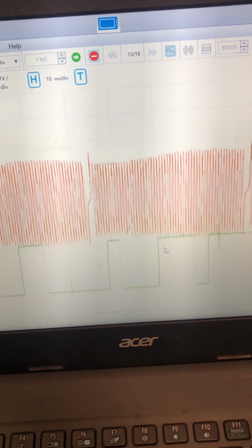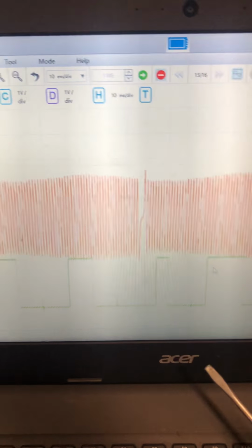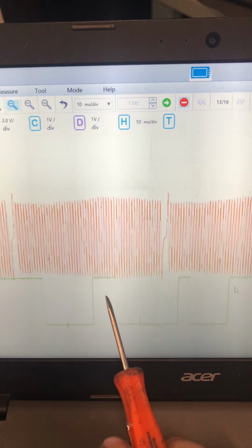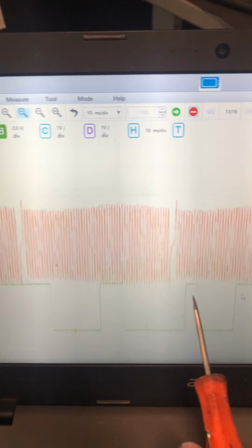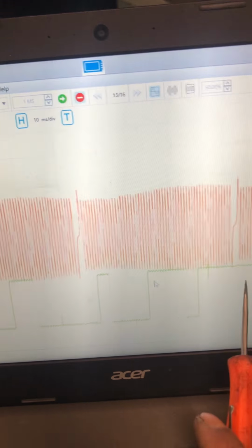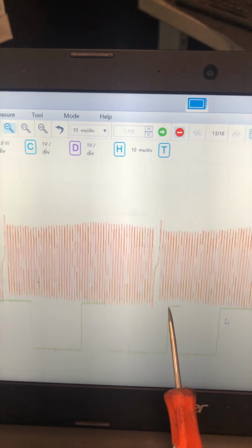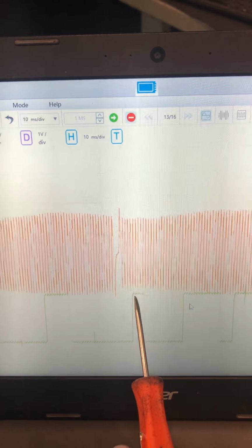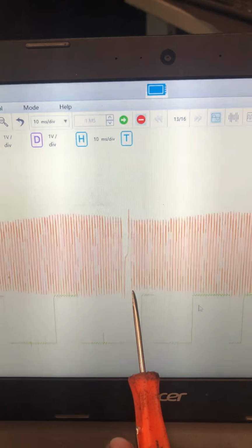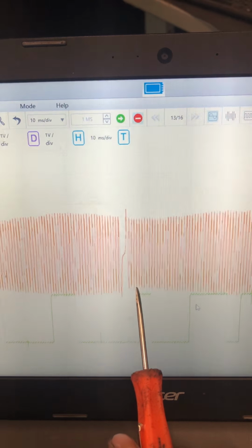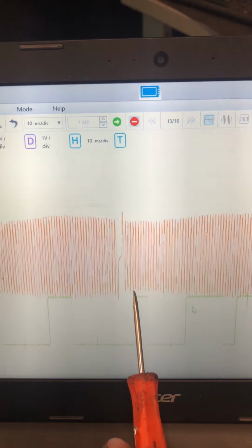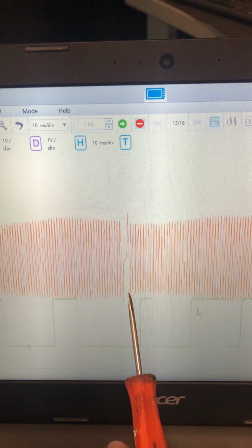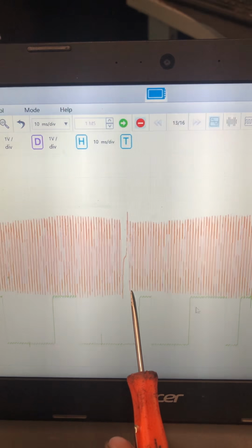Because this is zoomed in a little bit, we have a very small signal, a little bigger, and a bigger signal here. And as you can see, on our small signal here, it's a little bit away from the crank, right? Unlike on our bad waveform, where it was on this very first signal.